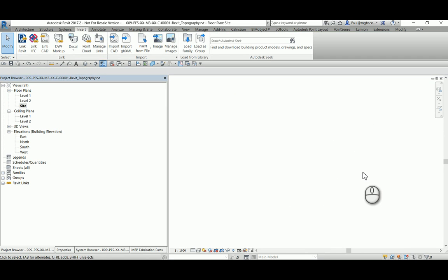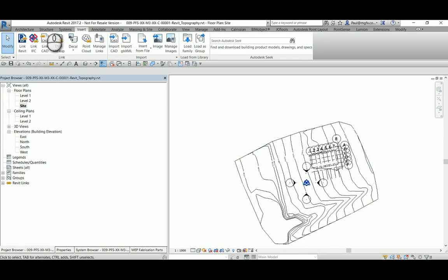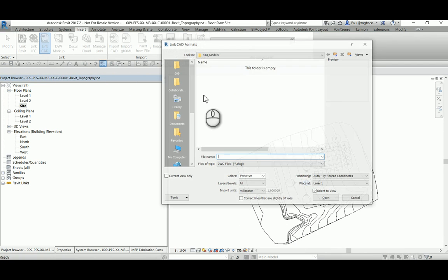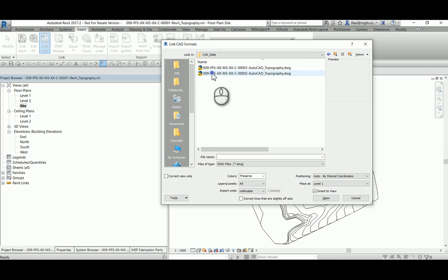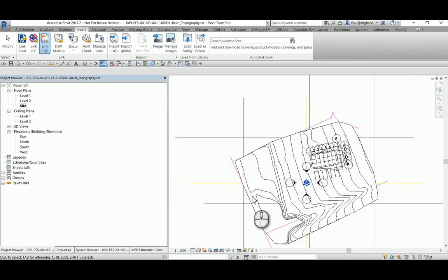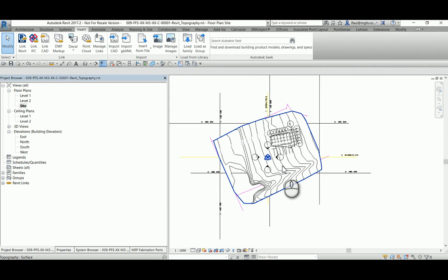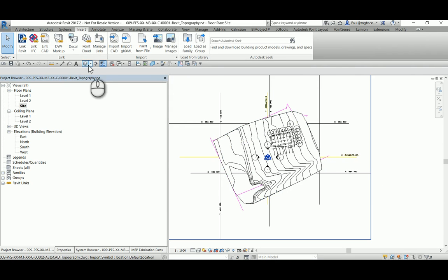That CAD file is of course now out of position. Let's just get that back in by shared coordinates. We link in the CAD, also by shared coordinates. That's great, that's easy now. Okay, so one can go in reverse just as easily.